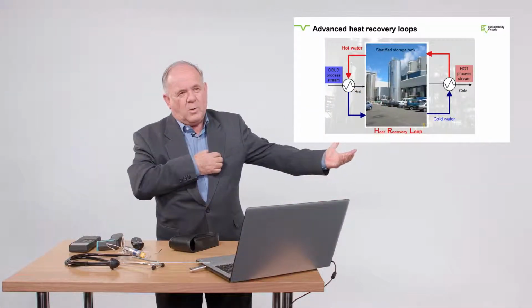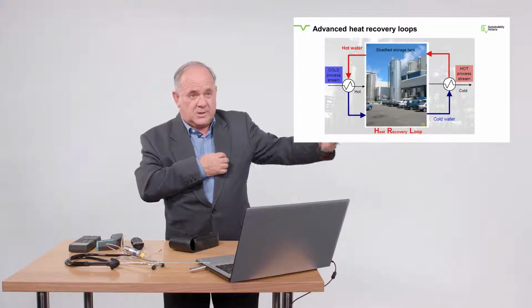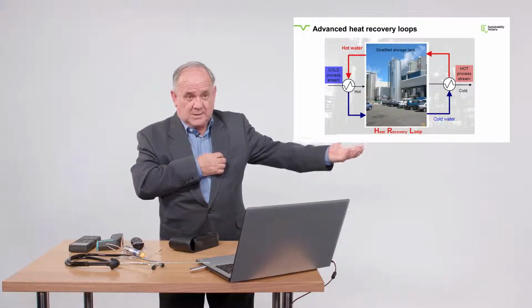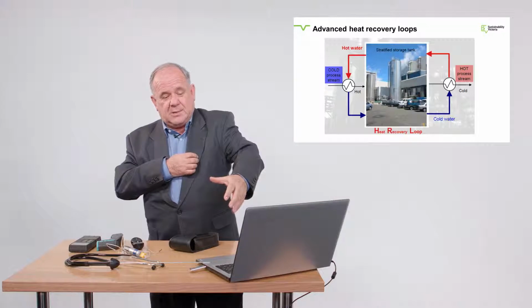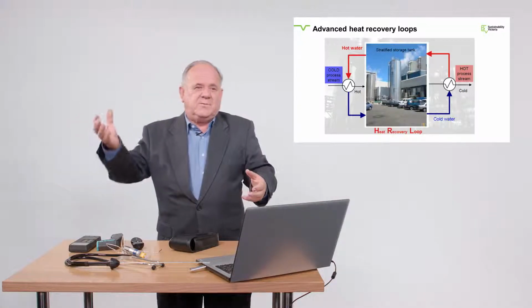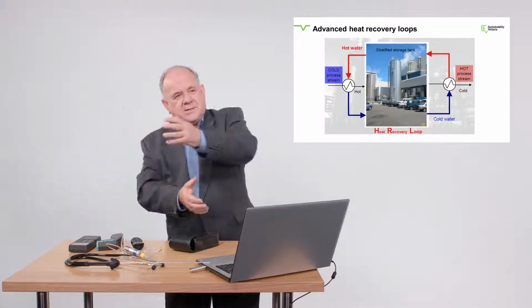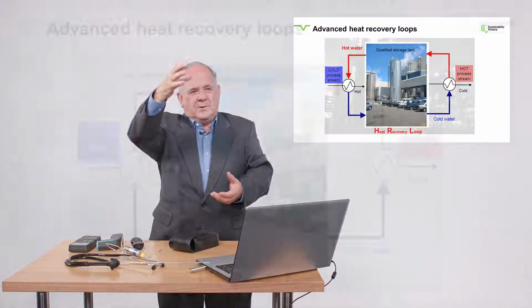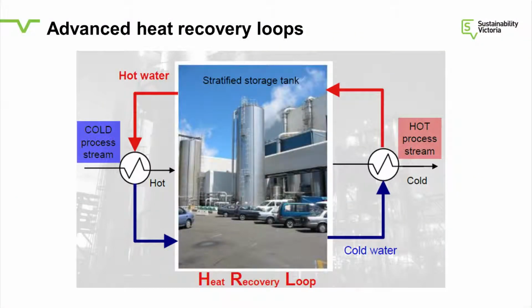What it does is take waste cooling from a process that would otherwise have to be handled, it gets put into the tank, it takes waste heat from the other, and then exchanges those. So you've got the hot water in the top of the tank, cold water in the bottom. It's stratified, and then you extract that heat and cooling for pre-cooling and preheating.